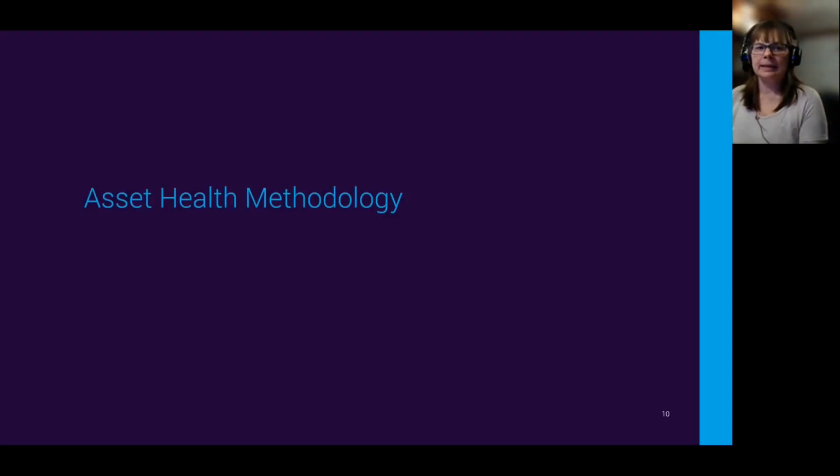So now we'll dig a bit deeper into the actual methodology. So as Chris said, this is based on the Common Network Asset Indices methodology, and we've got a link to that right at the end. We've got some links so you can have a look at that methodology if you've not seen it already. And it's, like I say, as close as we've got to a standard. There is nothing better, but if you do start looking at that or start implementing something like that, it will need adapting for your own environment, so for your own data points, for your own assets at your own voltages, and you'll need to calibrate the models.